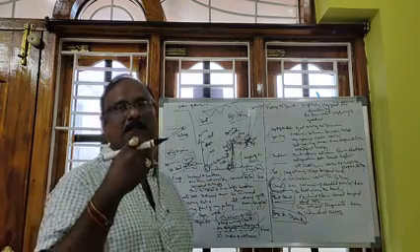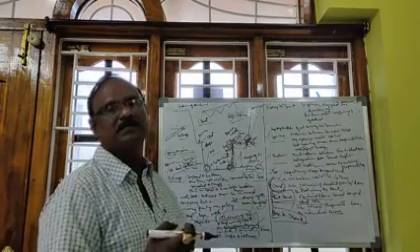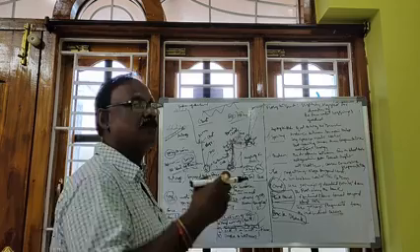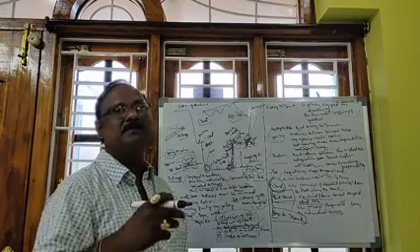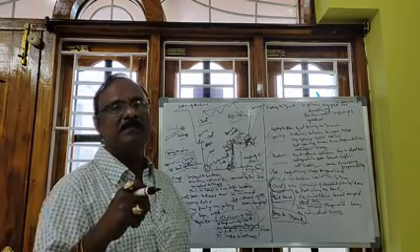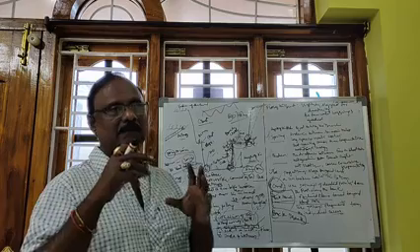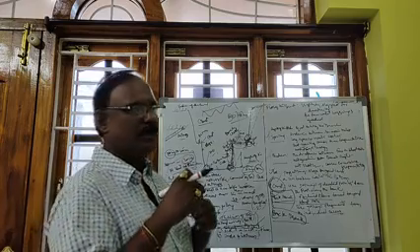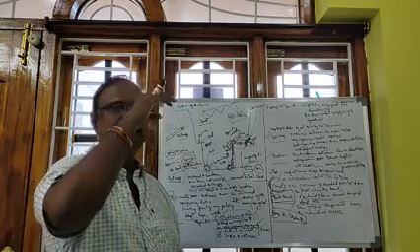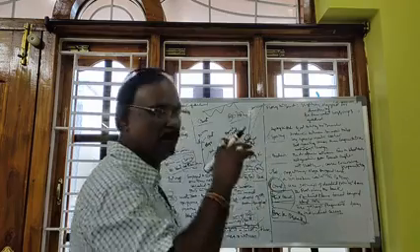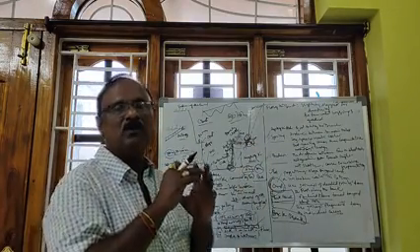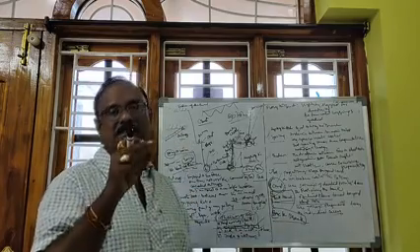When the strata are water bearing, with plenty of water, automatically the height of the bench is reduced. Suppose the height of the bench is more than 10 meters in a water bearing strata, slope failure occurs along the slope. The total slope falls down, the whole bench collapses, and a major accident may occur.